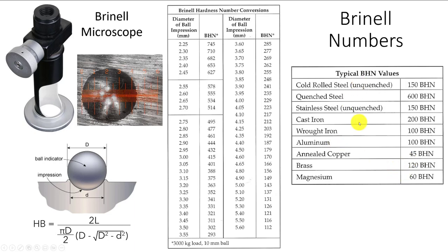And so I can see the different materials that we have. So again, BHN numbers. When we look up our material properties in MatWeb, sometimes they might list something as BHN, and we're going to have to convert, especially when we're looking at the heat treaters guides in terms of tempering and stuff. They won't always have Rockwell B, Rockwell C. They're going to have Brinell, Vickers, and we're going to have to convert. And there's an episode on how to use the links and access that. And we'll even talk about that again here towards the end.